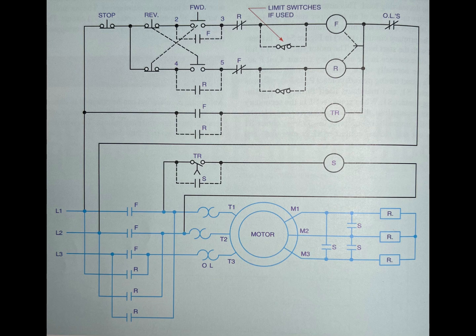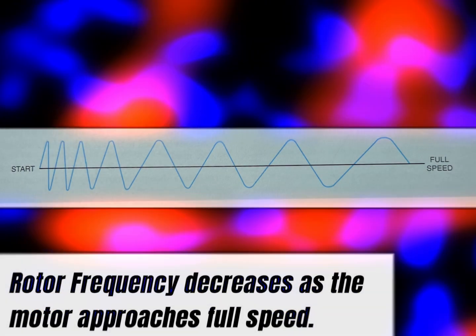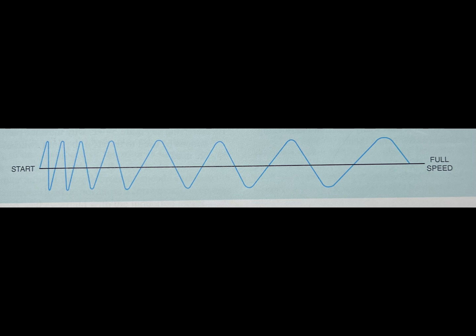The above image illustrates a simplified frequency relay system operated by a push button starting. This system has two contactor coils connected in parallel, A and B, and a capacitor connected in series with coil B. A 3 step automatic acceleration results from this arrangement.